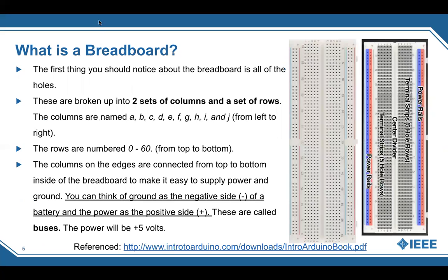And now I'm going to get into the breadboard. So this is going to be a little of 201, and you'll see why I'm talking about the breadboard with Arduino. So for the breadboard, you need to notice it has holes throughout it. There's a hole here, here, here. They're all along this board. And basically, we have columns and rows.